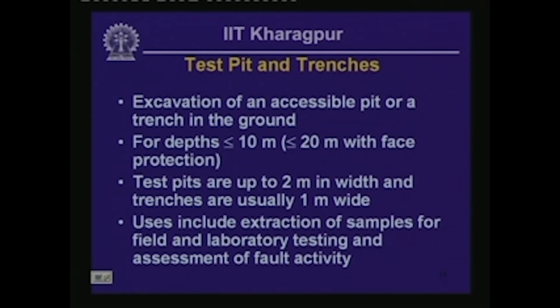So, this particular type of procedure is used for investigation of shallow soil and rock layers, or in some cases the depth of investigation can go up to about 20 meters, but in this case the sides of the excavation cannot be left unsupported and some temporary support has to be installed in order to take care of the stability of the sides of the excavation.